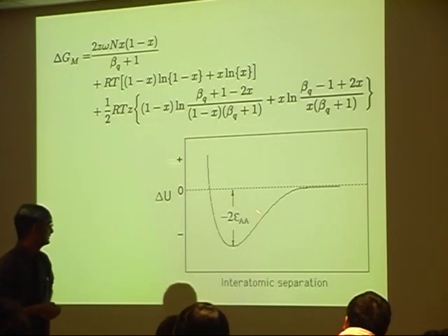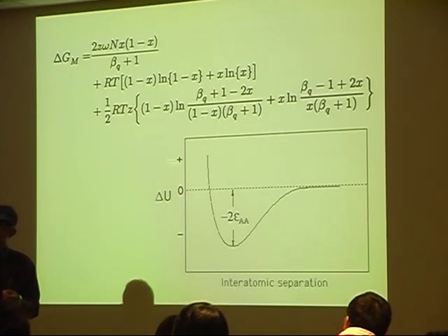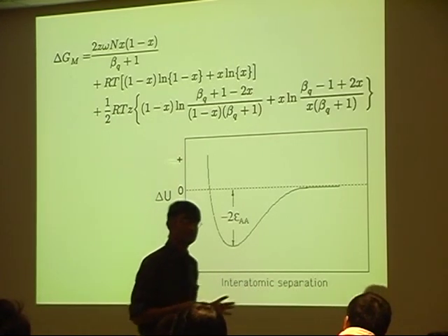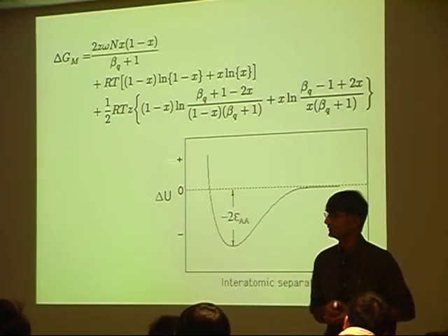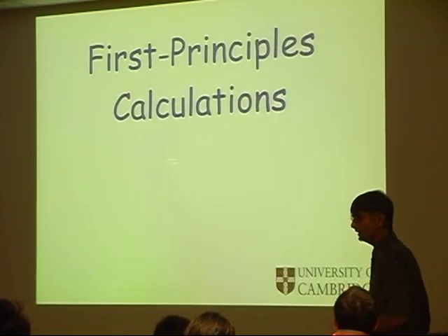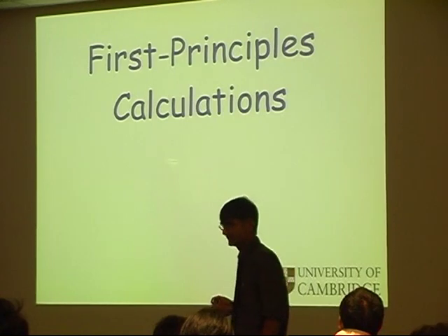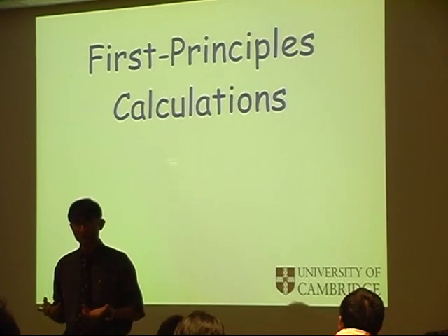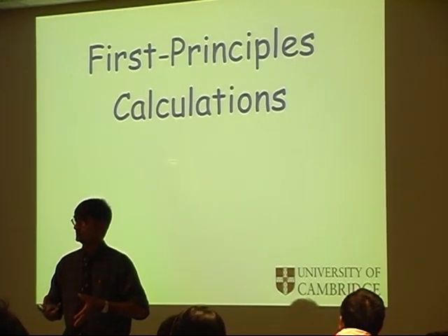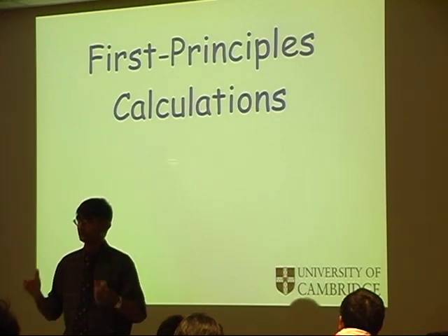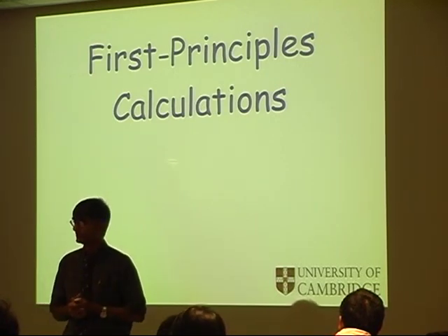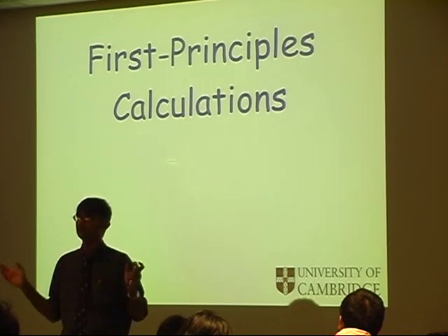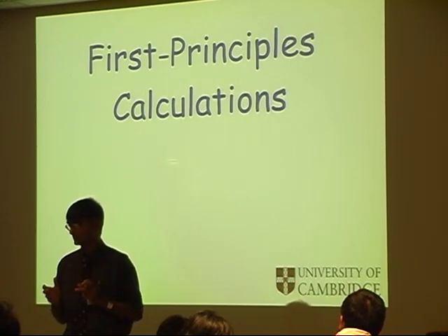Now, sometimes these data, the binding energies, are not available experimentally, but you need them to do the proper calculations. So how do we proceed? Sometimes the experiment may not actually be possible. Well, we then start to use electron theory. Right? Now, electron theory allows you to calculate bond energies, elastic moduli, the crystal structure. So you can say, okay, I want iron in the diamond crystal structure. What is the cohesive energy of that? You can do that calculation even though iron doesn't exist in the diamond crystal structure.